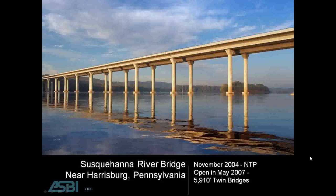Now I want to move into precast span-by-span superstructure construction. This is another method for building precast segmentals. Talk about the Susquehanna River Bridge in Pennsylvania. Notice to proceed was in November of 2004, and it was opened in May of 2007. It's twin 5,910-foot bridges, very, very rapid construction. The typical span length for this bridge is 150 feet. It also has an integral wearing surface.